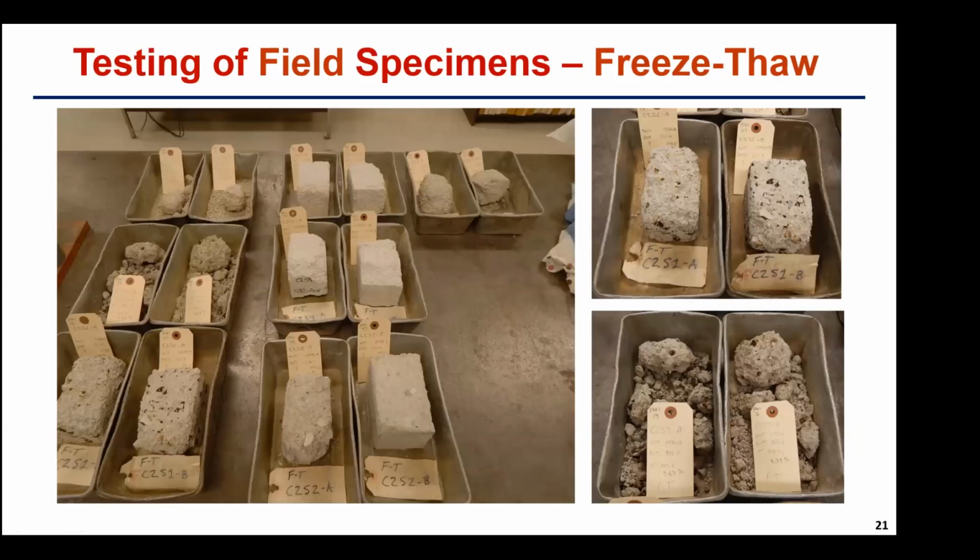Now this is showing, again, the test for freeze-thaw durability for the lab samples. And I'm showing here on the right side of the presentation some of the best performing samples. Sale 2, section 1, that's QB with RAP. It's not necessarily the best performing, but one of the good performing samples. And then some samples that disintegrated before 12 cycles were completed. And that's where you have to extrapolate the curve into the 12 cycles to get the average estimated soil cement loss.